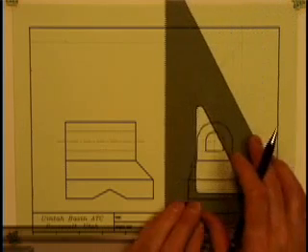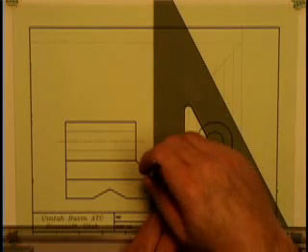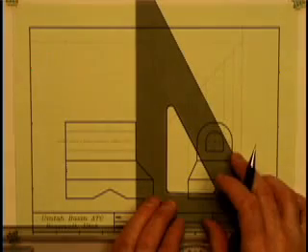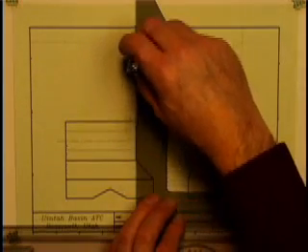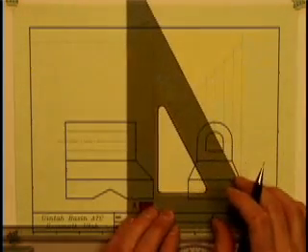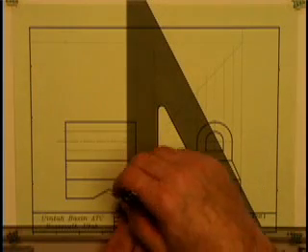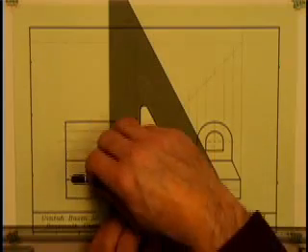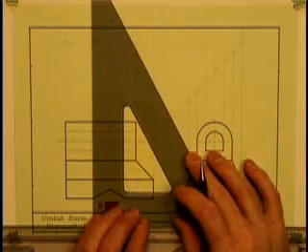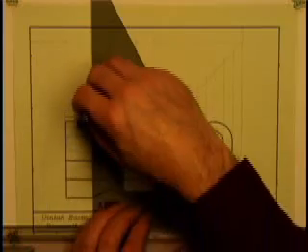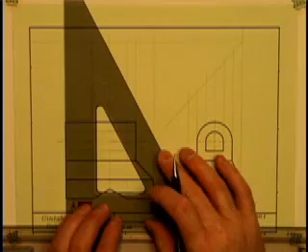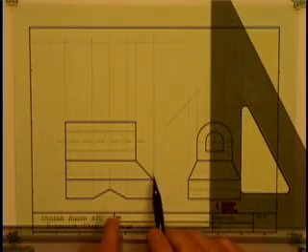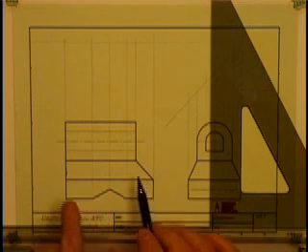Now we will go to the front view and we'll just continue. So we'll take the front edge of the front view, project that up, and each time we bump into a new feature, we'll project that line. Oh, better have the start of the angle down here. Got to project that. Top of the angle, better project that. Other side of the angle, better project that. And finally, we'll take the far end of our object. Okay, so we've projected all of the features that we found in the front view.